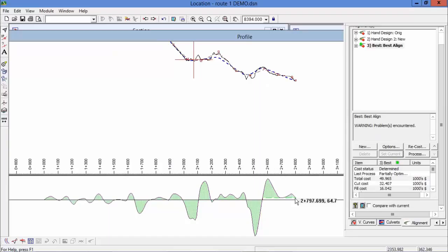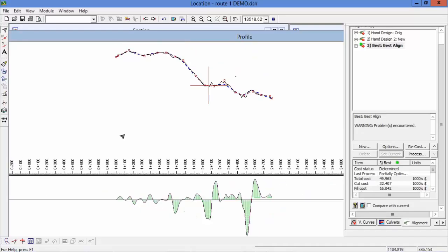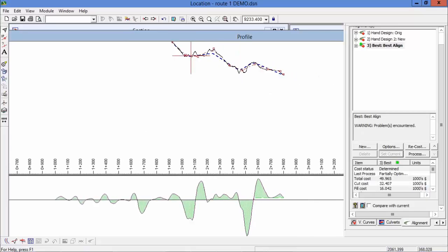Qualitatively, the mass flow diagram looks much better. You almost have no earth movement, and at the top here, the excess of cut and fill are never very large. So this is definitely qualitatively a much better alignment, but this is confirmed by the costing procedure that we have.